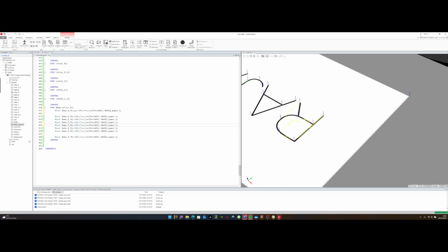Okay, and I'm doing everything like this in rapid. So again, we've moved J to the top, move L takes the pen here. This next move L to R20 takes the pen here. This next move L to R30 takes the pen here. So now we want to move C like this. So I'm just going to come over here.